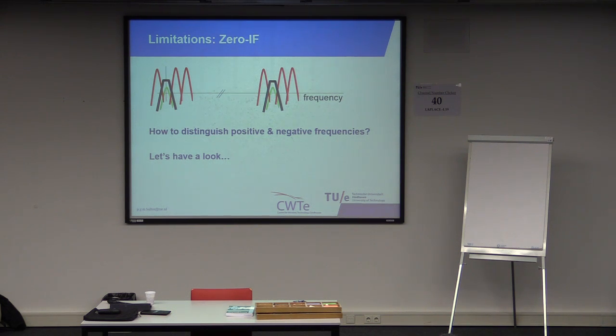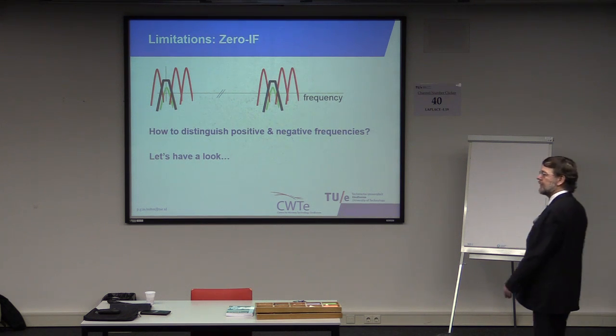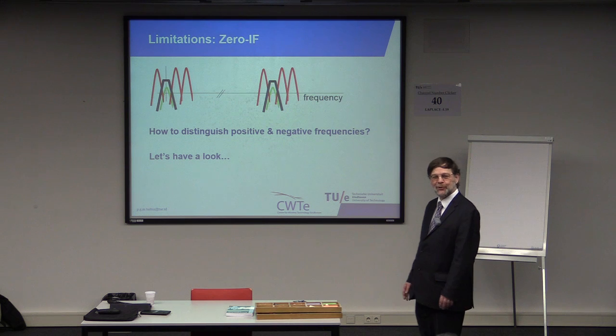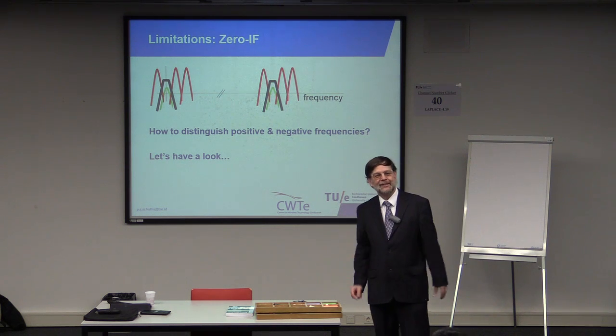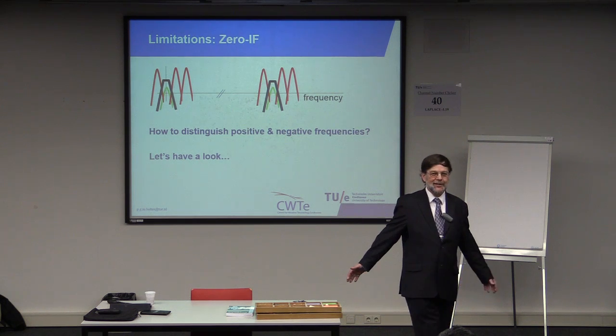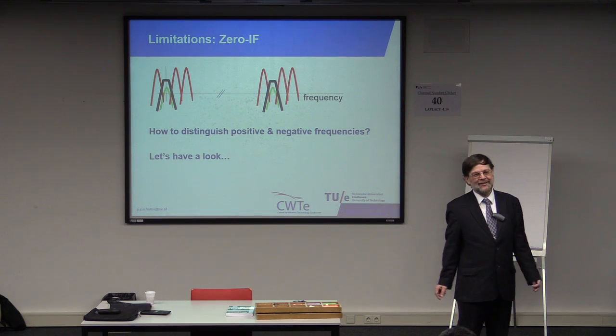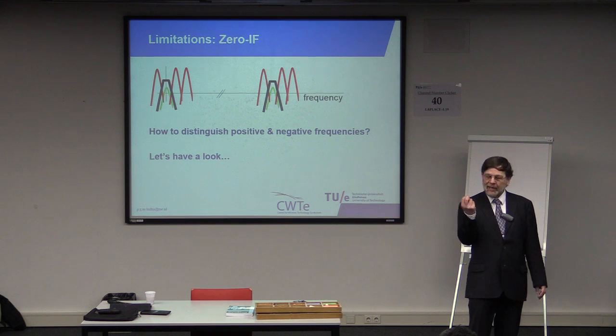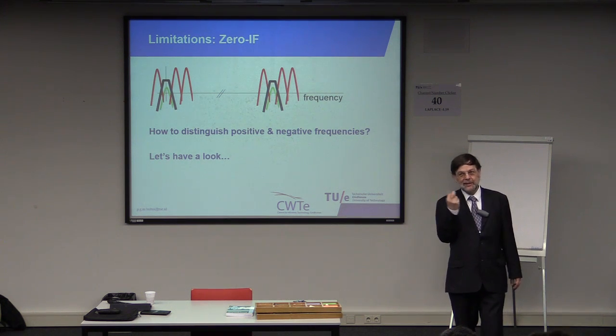Anyway, if I have a signal, I have a signal generator. I measure what's coming out. How do I know where t equals 0 is? Who tells me? I mean, if we're serious about that, t equals 0 happened some 4 billion years or 6 billion years ago or so, when there was this Big Bang. But we don't know it to the nanosecond accurately. So for gigahertz signals, this is not really helping. So we don't have an absolute time reference that tells us when t equals 0.